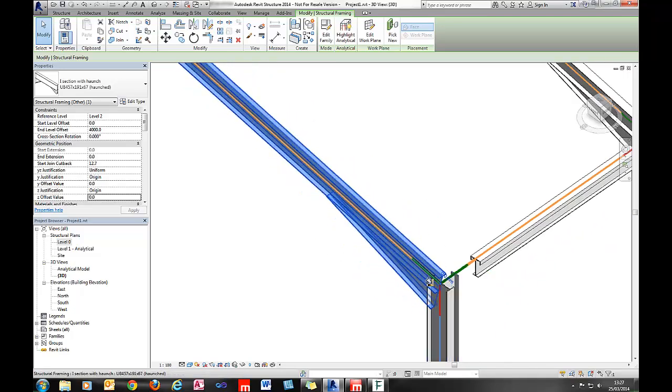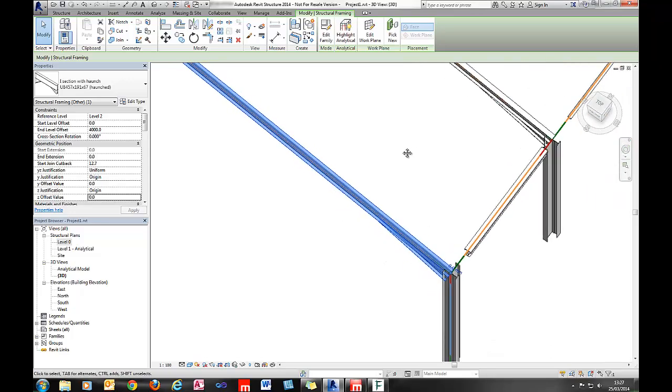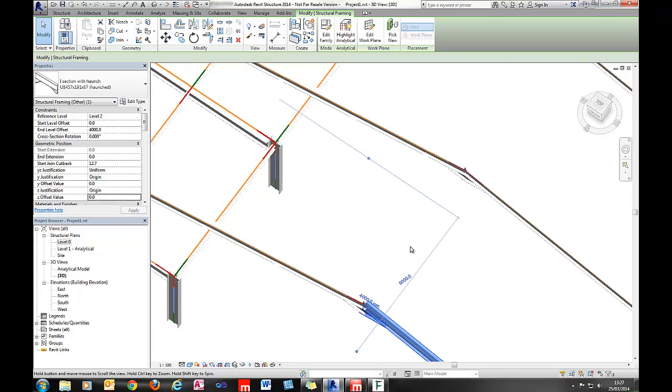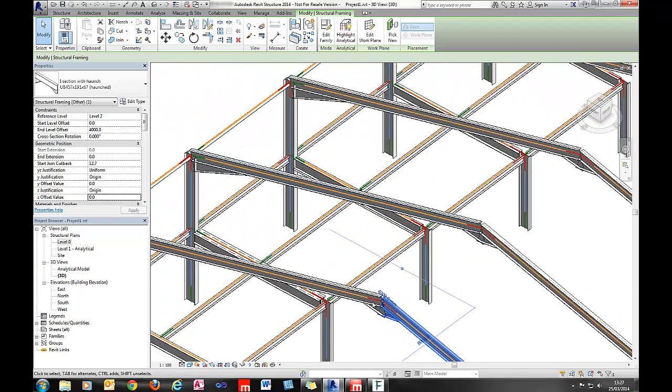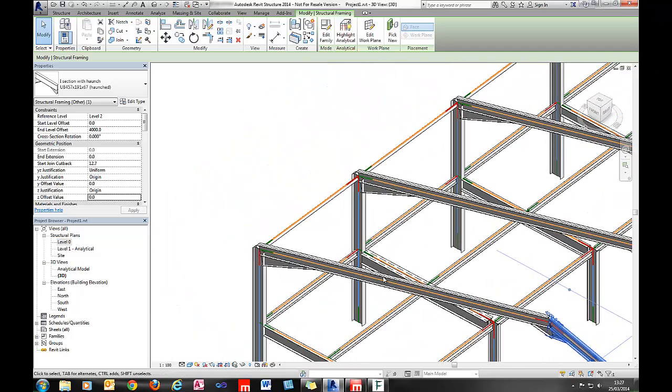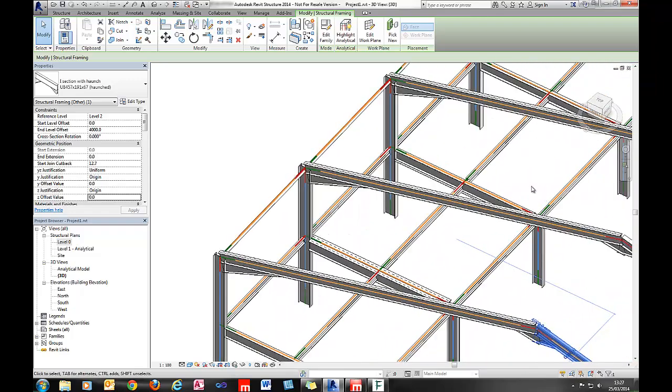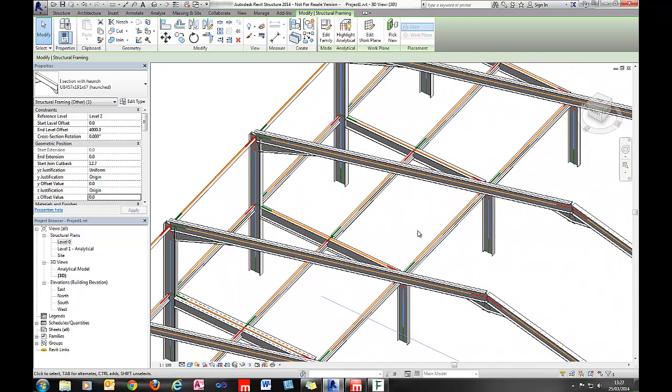So with this information, basically, you have an accurate layout of how the actual haunch might or should be cropped and end plated, perhaps, if you want to get into that level of detailing in Revit, without wondering, well, is it actually moved? Because if we start to justify this to the top of this line, then that does adjust the geometry that's created between the column and the beam, and it differs then from what you have in your analytical model and also your haunch geometry layout.